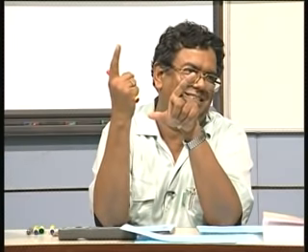Now, let me tell you, in the FDLF, there is some sacrifice in accuracy. After all, you have ignored those off diagonal terms. So, when the attribute becomes accuracy, there is nothing to beat Newton-Raphson, because you are not ignoring anything in Newton-Raphson. You are taking the system as it is, as it stands, as it exists.